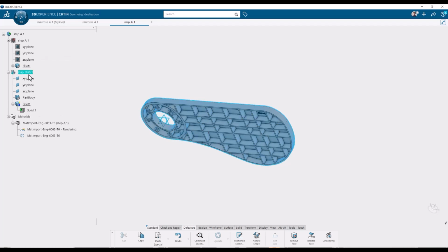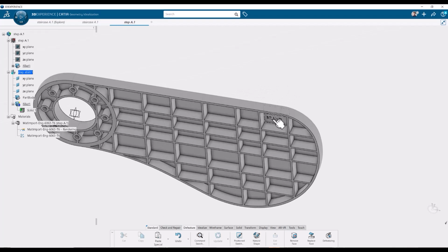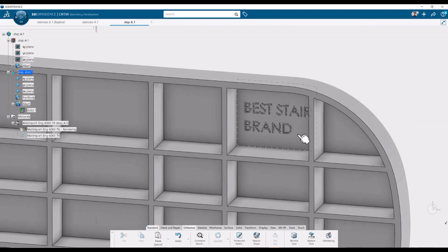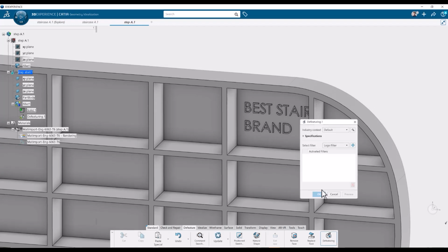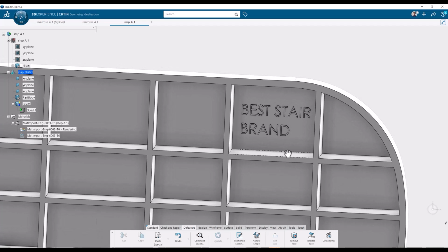So here in the abstraction shape I can now do some modifications. The logo, we don't want to have to mesh this one. We can tell the mesher to ignore logos in some cases. We can also use the defeaturing tool here, which works for some logos. For some logo filter it's possible to take it away. For some cases you might have to do it the sort of manual way. So let's just do a pocket or a cut extrude here.